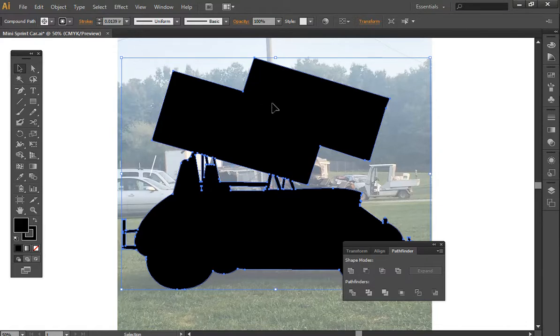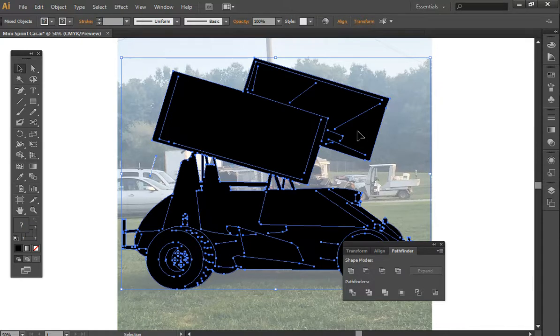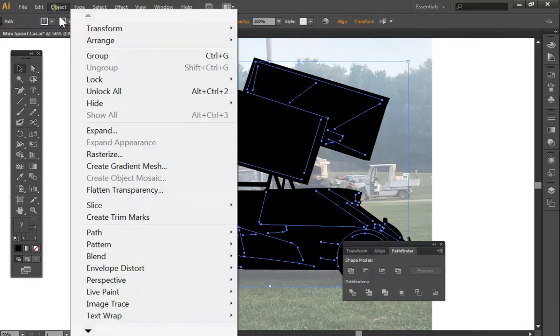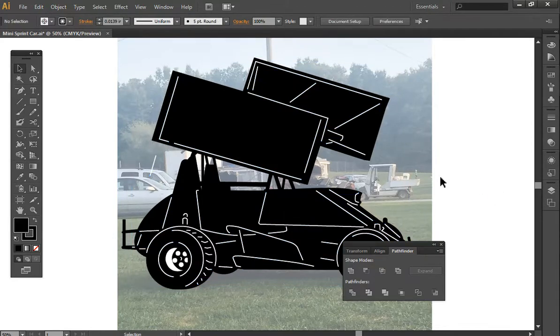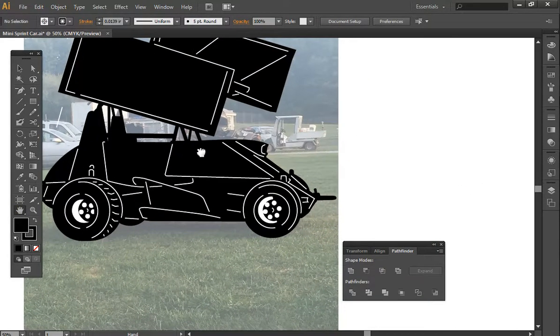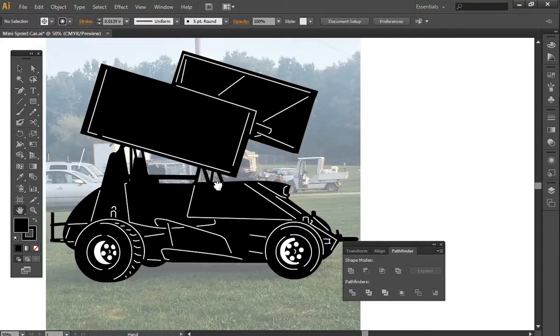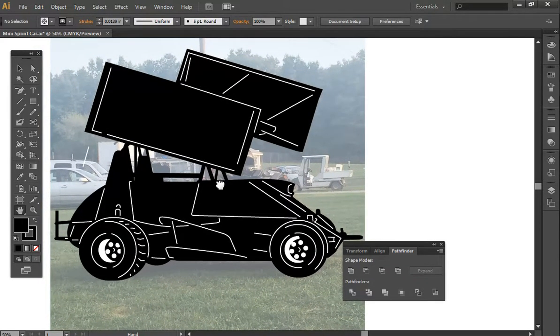Illustrator works in layers, so there's actually multiple layers. Your main artwork is going to be on the very back layer, and anytime you create an action using unite or minus, it's going to bring it to the front. So what you can do is draw this big bounding box around everything, and then hold the shift key and select the main silhouette. Now you have all the interior details, and if you go Object, Arrange, Bring to Front, that's going to bring all that detail to the very front again. So that is getting very close to being done with this particular design.